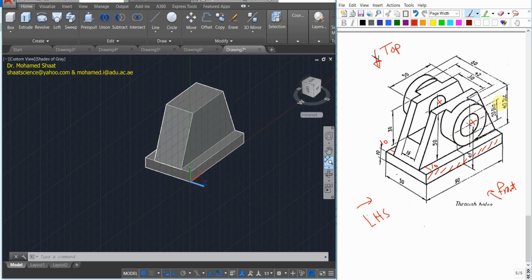In the beginning, I'm just gonna create this cylindrical outer, with the outer diameter already given as diameter 40, and this cylinder should be extended from that point to that other point, extruded, and it won't be subtracted. So you have to stick to the dimensions, and the length of this cylinder should be 60, and this 60 should be typically in the middle.